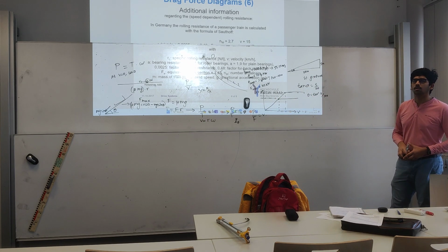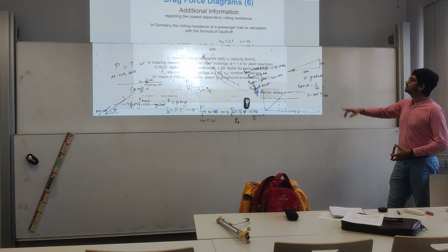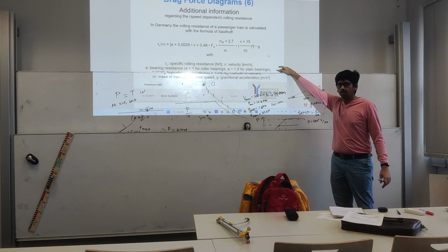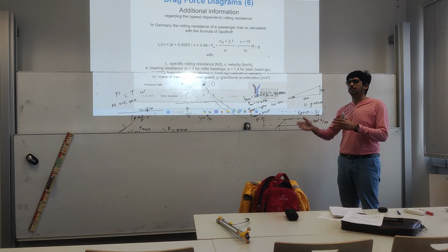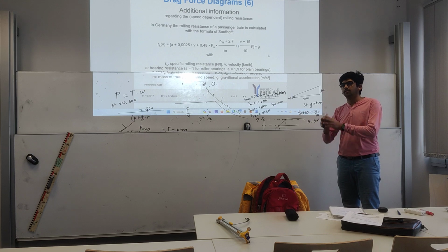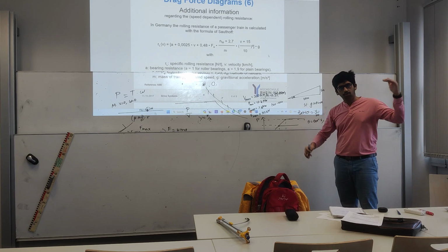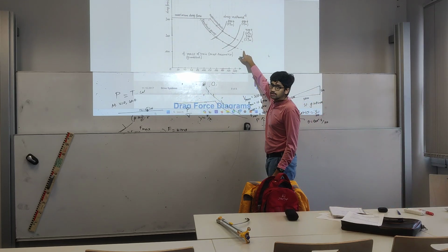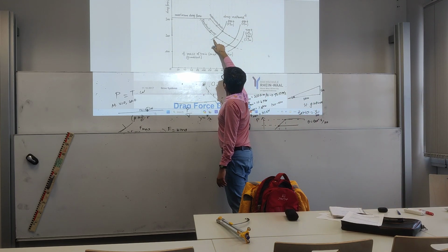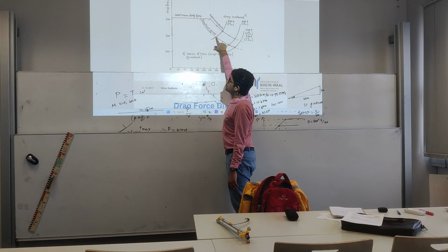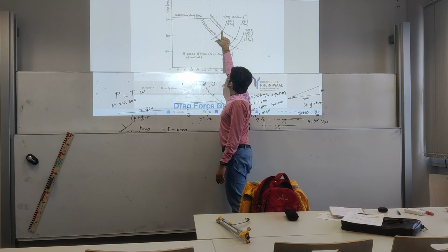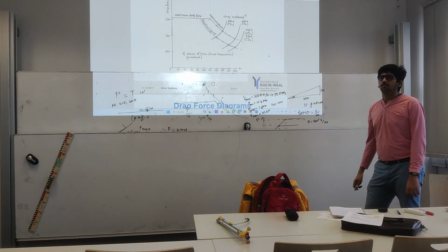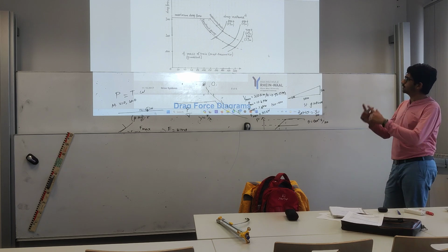But I still don't understand how do I read those three lines though? Those three lines have been drawn in advance based on this equation, and those intersection points tell you where it's going to stop accelerating, which gives the top speed. So you draw the drag force line as per your calculations, and this line you have drawn based on that equation. And this intersection point gives you the top speed at this power, and that top speed is at that power. I see. It's like a 3D graph at that point. No, it's still 2D there because you just have intersection points.